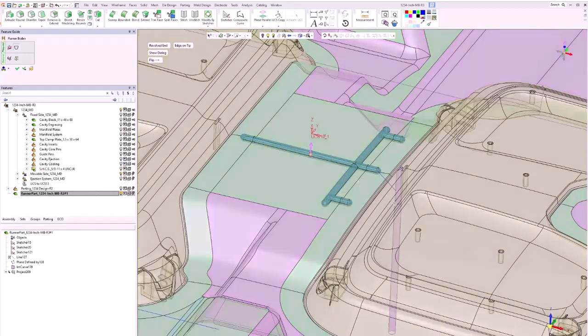The last option that we're going to look at is cold wells. So it added them to the end of the cross runner, but the short ones do not have a cold well. So I can select under option 2 cold well. You could have an auto length that you predefine in preferences, or I can have it on manual, and then I can select the X's here to add the cold wells on the end of the short runners. Again, they're manual, so I can control them how I want. Once I'm good with it, I can say OK.